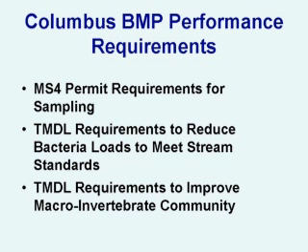In the leaf season we get a tremendous amount of leaf load, but what we found, which is so significant, is that we're getting about 7,000 pounds of sediments, and this is organic and sand and real fine sediments that are trapped in this facility that are removed on about a once every 2-month basis.